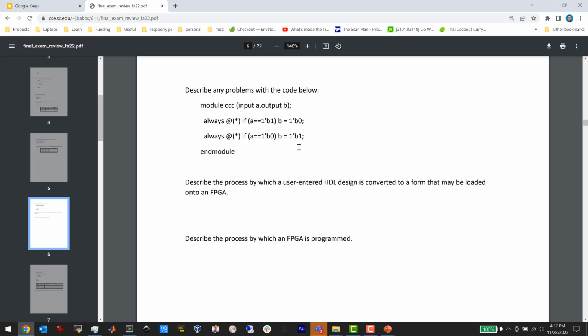So those are radically different problems to solve, right? Those are the basic two steps. There's the mapping phase too, where the netlist may assume that you can do LUTs of any size. So you may have a 10 input gate in this netlist, but you only have 5 input LUTs on the FPGA. So now I have to split the 10 input gates into multiple 5 input gates. So there's a mapping where you have to map from one set of primitives to another set of primitives. So there's a mapping step in between as well.